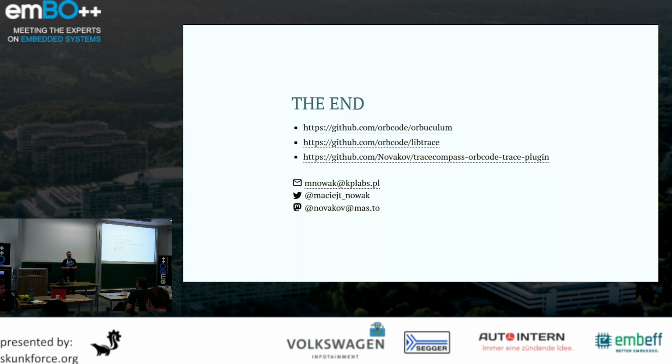I don't think so. I don't remember any mention of RTT. Okay. Then we maybe should change that, because why I'm saying this is, if you bought the J-Link and you got the tool with J-Link, you will have the RTT as an I/O channel to extract such data, even without using additional pins like SWO or parallel trace pins. We can just use the debug interface that you have designed, so your hardware designers will be happy, and you reduce the overhead that you have with instrumentation by like 100 times.